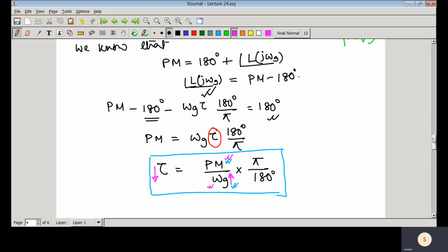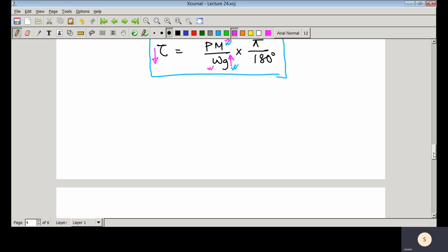So now we are going to discuss one more concept. Whenever we studied first order and second order systems, that is time domain analysis, there we saw how to characterize the system, or how to define the specifications of the system. It is defined in terms of percentage of overshoot, settling time, delay time, peak time, or damping ratio. So those terms are the time domain specifications. Whenever we want to specify something in the time domain, it is characterized by those terms.